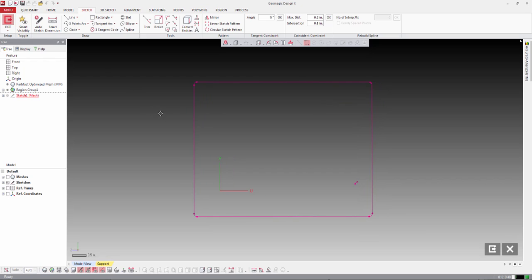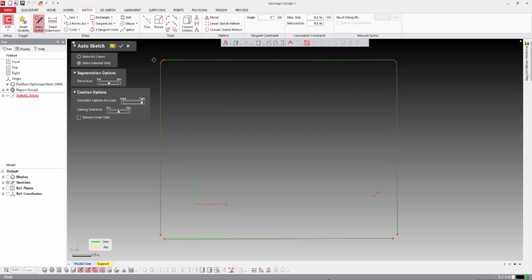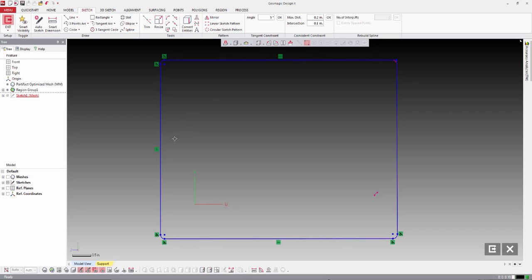And what we can see is that we've got this polyline. It's called a polyline, and we can actually fit geometry to the polyline. So we can fit lines and arcs to the polyline, and what happens is constraints are added, like horizontal constraints. We can add fillets if we wanted to. We can add a sketch fillet. We can dimension this sketch up if we needed to.